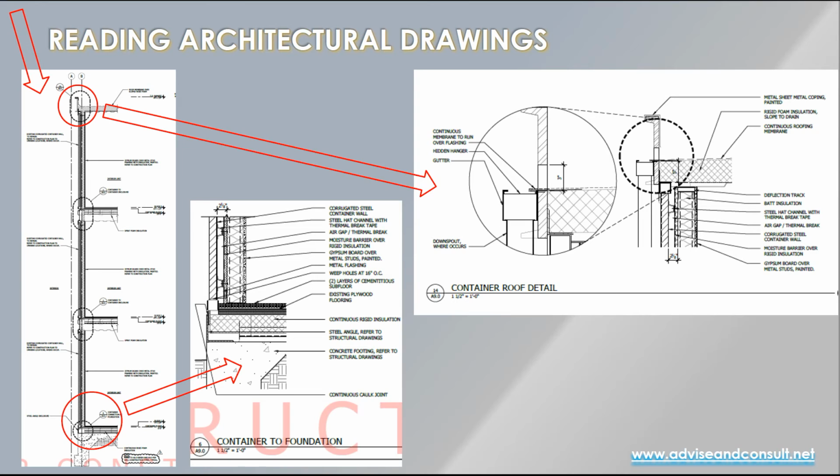Similarly, the parapet at the top of the building, and you can see I'm directing you here from the parapet detail to that actual detail drawing on A9.0. And here we are at the detail, and an even closer look at that detail drawn because of the specifics of water penetration. Architects think about water every single day, all day long.